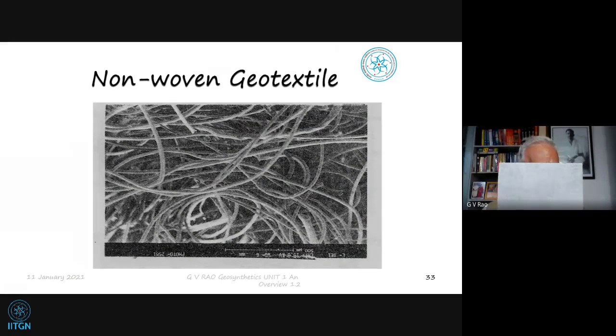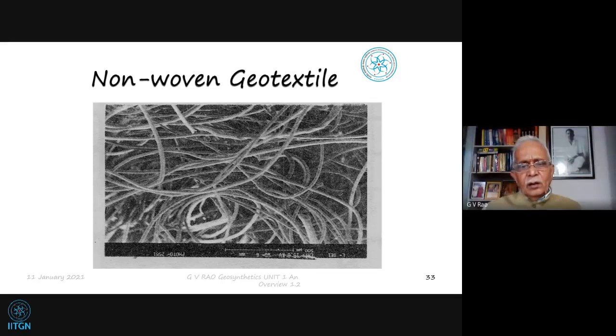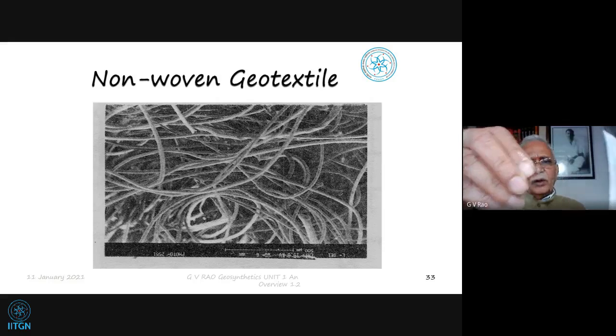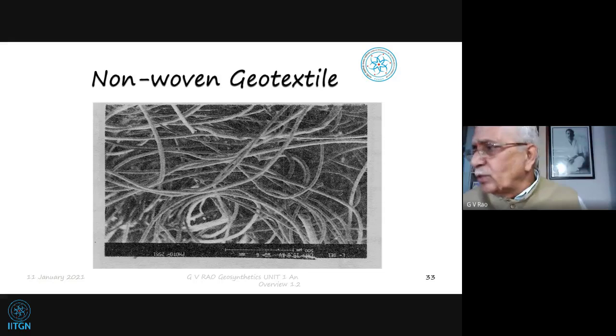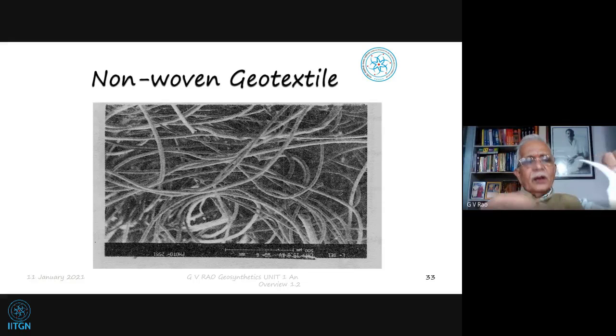Okay, there are also other products, partially thermal and in one single go. So this is also another product like this now. And wherein we find that there are all continuous filaments. You can see filaments keep coming out continuously as you keep removing it. You can see it's a continuous filament. Okay, you can't see clearly, but the filament is just continuous. If you think of trying to do the same thing for a non-woven geotextile, normal staple fiber geotextile, we find that we can't get it like this. You see, it simply breaks. After some time, it just breaks now.